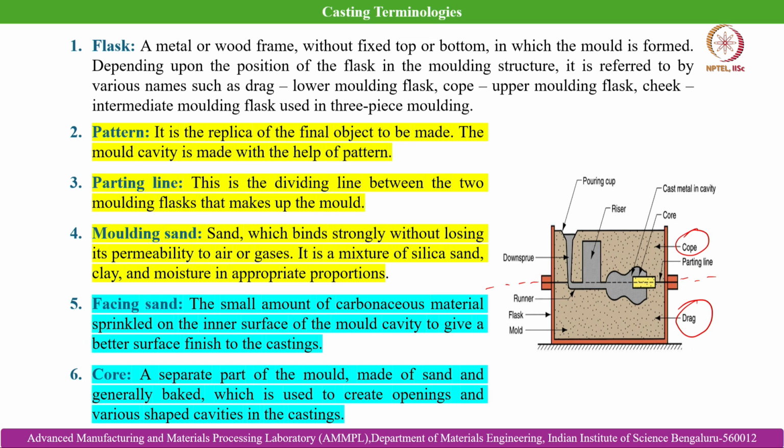So, the sand grains which are used here. You can see the sand grains over here. This is basically called the molding sand. The molding sand should be of sufficient quality, and it should be free from moisture, so that it does not cause gaseous emissions, whereby gases can be trapped within the mold cavity, and that can cause blowholes and also gas porosity within the solidified cast part.